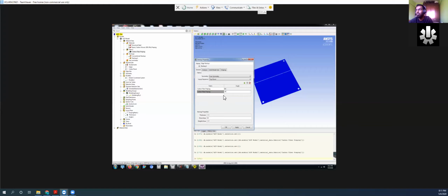And then another carbon fiber prepreg, 0. Because this is an even symmetry and I'm doing 6 plies, I need to do 3. What happens is that ANSYS will mirror it automatically around this line. For example, after carbon fiber prepreg, what automatically gets populated will be carbon fiber prepreg 0 degrees, carbon fiber 45, carbon fiber 0. So it's all mirrored along this line here.